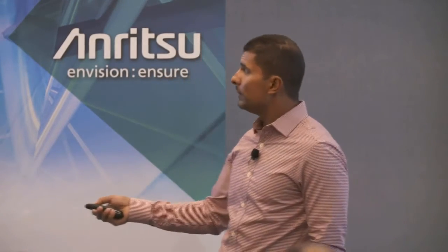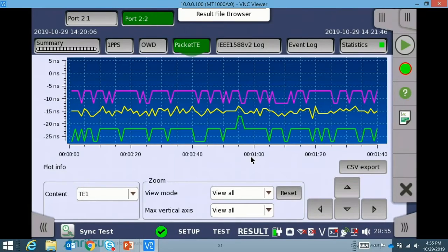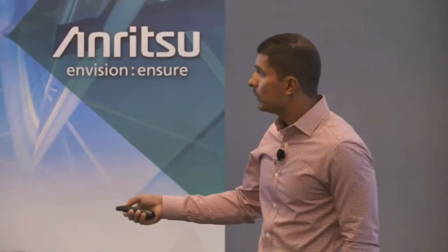So what you're seeing here is the min, max, and average timing error of the tester itself when it's measuring how fast it can remove the packets or strip off the timing, adjust its offset, add the new timing, and resend. So in us, we have an average of about minus 15 nanoseconds. So it's basically saying it's always behind by minus 15 nanoseconds timing error. With the worst case of around minus 25, best case you're looking at a little over minus 6, 7 nanoseconds.